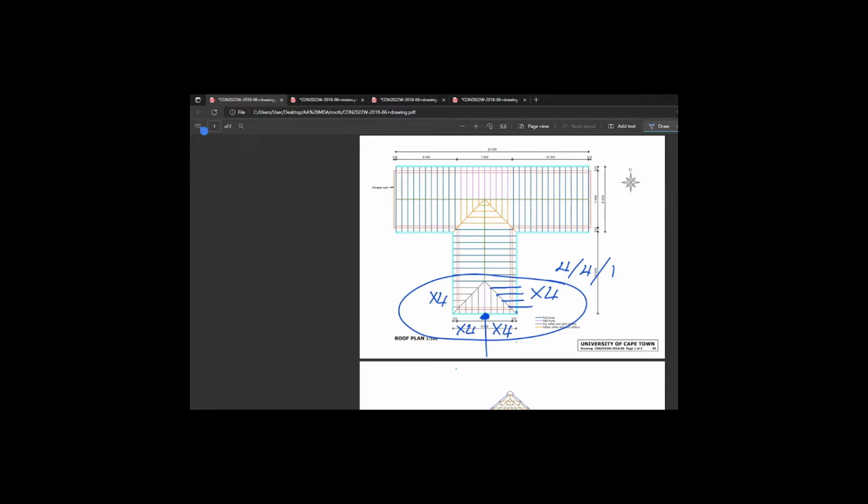Let's just take a look at the jack rafters and places where they will meet brickwork. Now remember we said that this was a full one, and this one's also a full one, so is that one. Despite it looking smaller on plan, we've considered them as full trusses. So let's just make it full truss. Now the other jack rafters that we've accounted for are all floating. In my mind, they do not meet brickwork. They are in the air, either suspended by our valley rafter or soon to be ridge beam. And in this case, is another ridge beam, right? So there's no hoop iron on that side, only here.